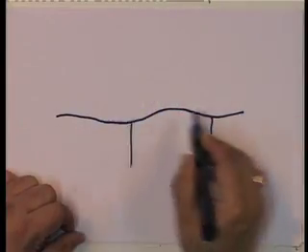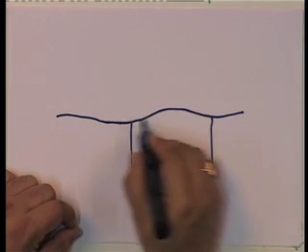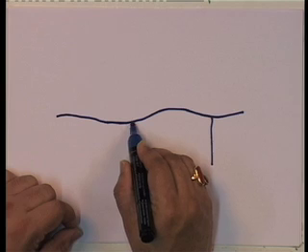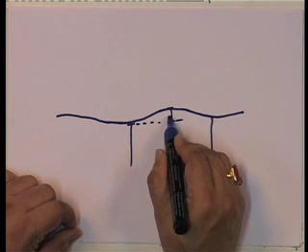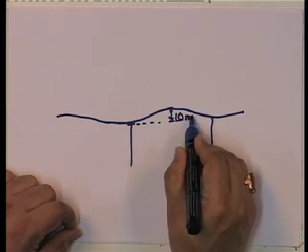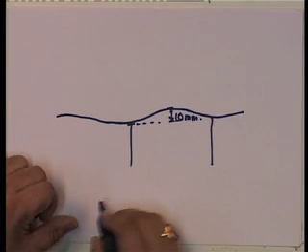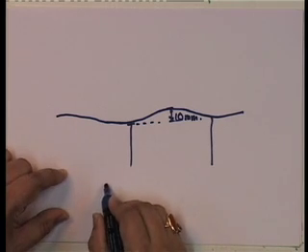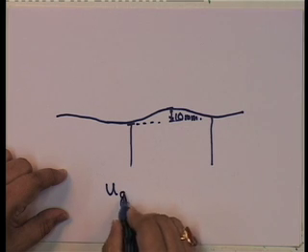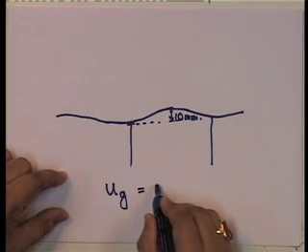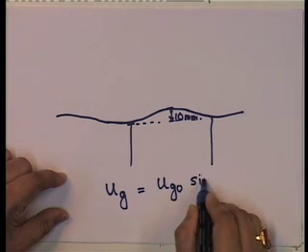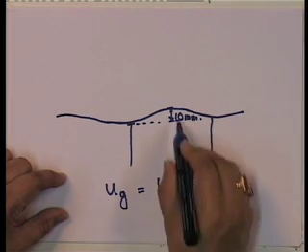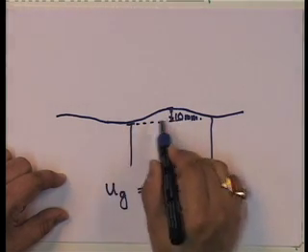So, I will call this that. So, the road surface is essentially, from this to this is 10 millimeter, and we will say that therefore, the base, which is the ground, can be given by UG0 sin omega bar t, where UG0 is not 10 millimeter. 10 millimeters from the bottom to the top is peak to peak.